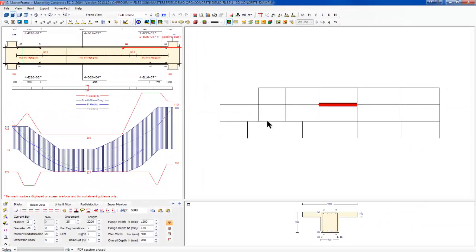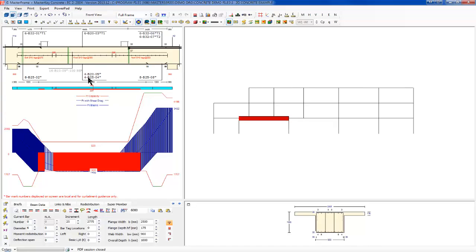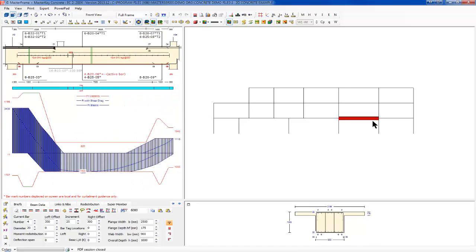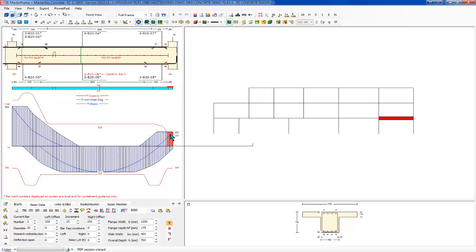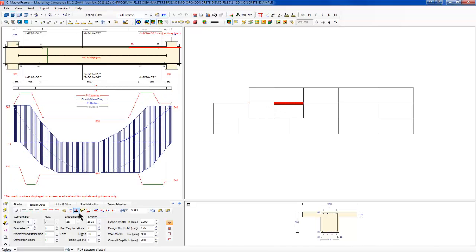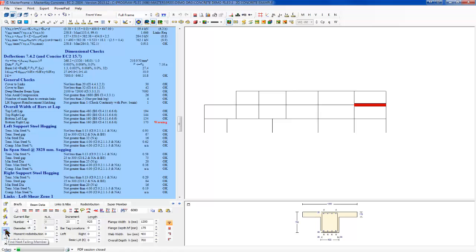So coming back to our first member, or our second member, we can see here we've got very heavy reinforcement. We're into possibly putting in additional reinforcement there, and we really want to just walk through and check that everything works. Everything appears to be working elsewhere, and we can see here, we're just ever so slightly over, so we'll put in the 20s at that point and walk through and come along. And we can also ask the program to run through and find them for me. So there is a button, if I can remember where it is, find next failing member.